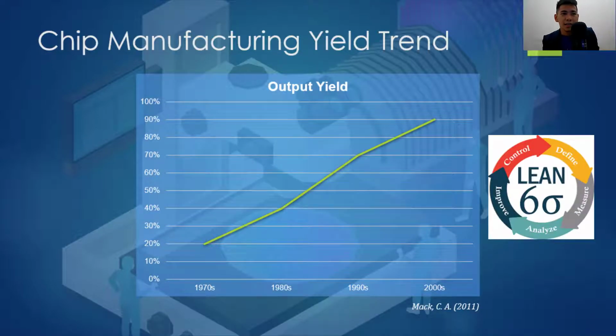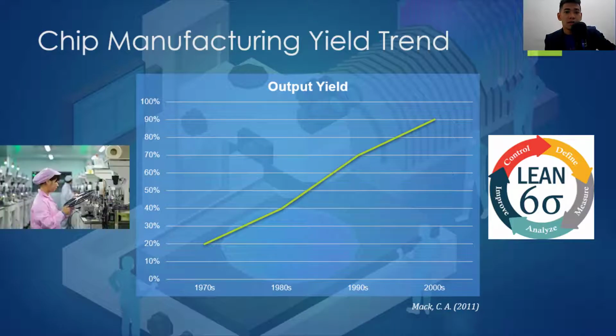Just to clarify these terms, we have a term like defected unit from electrical rejects, which means that the quality of the unit is below the set standard, is not accepted, and should not be shipped to the customer. And there are manufacturing rejects that can be avoided, like setup-related failures, test program-related issues, and electrostatic discharge from operators. If the overall rejects are significant enough, reducing these rejects due to manufacturing errors has been a critical part of yield improvement. By the 80s, yields were around 40% and went up again to 70 to 90%.